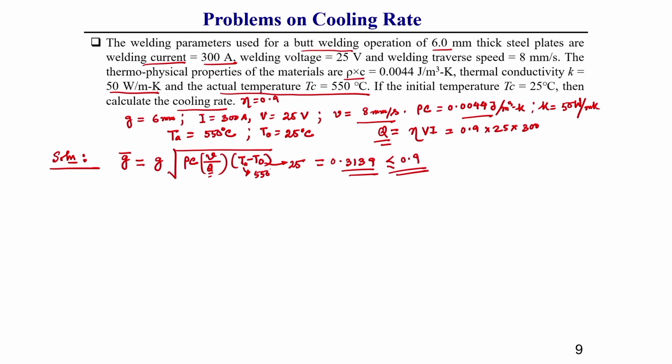What type of heat flow is there? This is a 2-dimensional heat flow. So, for the cooling rate calculation we need to use the 2-dimensional cooling rate equation.